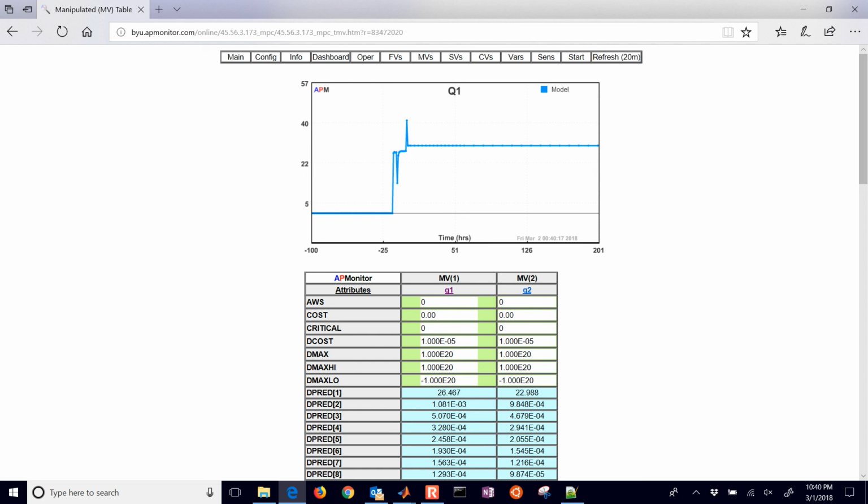Okay, but you can see the move plan for the heater. And one of the things with model predictive control is it's going to use everything, it starts at 0, and then it's going to make a move, and then it's going to implement that. Anything after 0 is just going to stay static, but you can see it's doing constant adjustments there just because the measurements are changing a little bit.